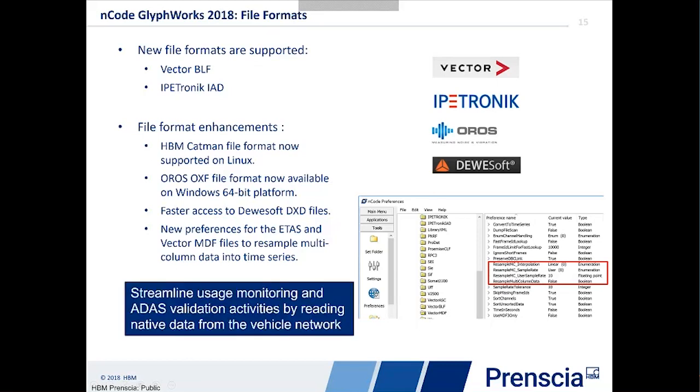Since you noticed most of the file formats have to do with CAN data, the idea is to streamline the usage monitoring type applications and the ADAS validation activities by reading natively the data coming from the CAN bus from the vehicle network.